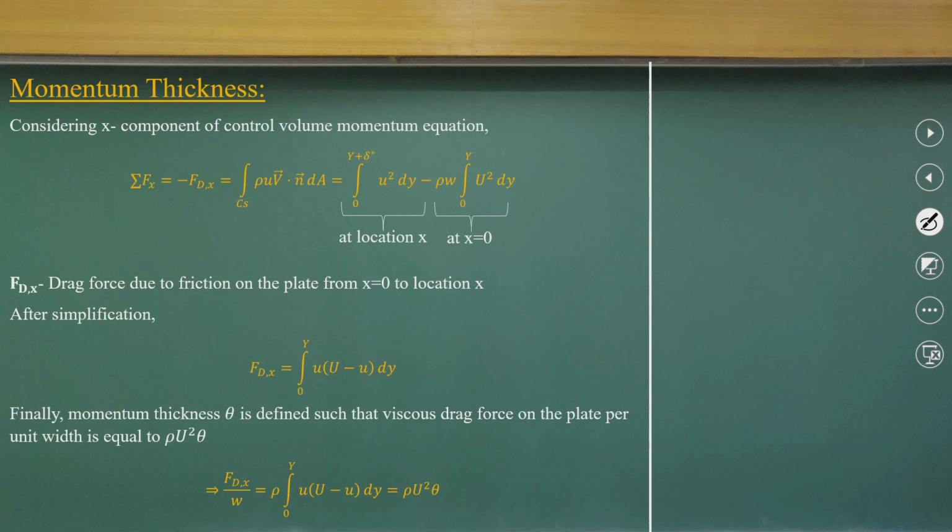Now we are applying it to this control volume: the sum of the forces acting is equal to the net momentum outflow flux from these cross sections. It is a two dimensional cross section. So we can define what the momentum flux going out of the cross section will be. This is in, this is out.